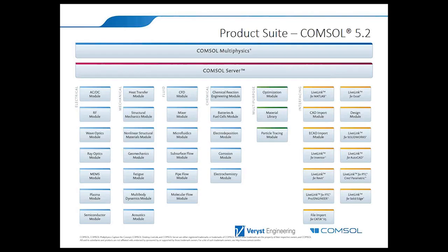Thanks. Yeah, there's several things that we do for that. So we do a lot of model verification. That is to make sure that the solver, the analysis settings, the mesh are all properly selected. Then for validation, we compare the results against any experimental data the client might have, even if that involves simulating different bench tests or animal tests.